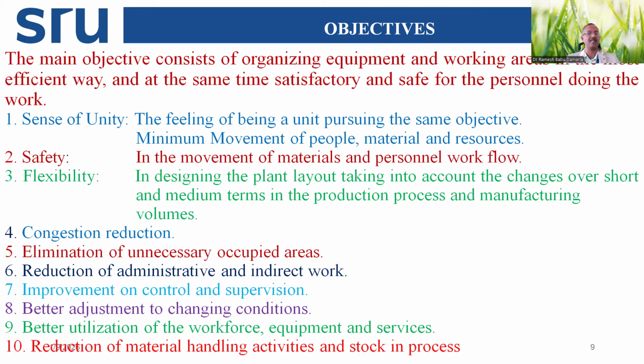And another objective is congestion reduction. So we should avoid any kind of unnecessary congestion. Then elimination of unnecessary occupied areas. Then reduction of administrative and indirect work. Unnecessary work must be avoided. We all know wastages. Wastage in machine time, man time, energy, unnecessary transportation, all this must be avoided by careful planning at the layout design stage.